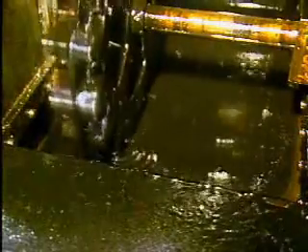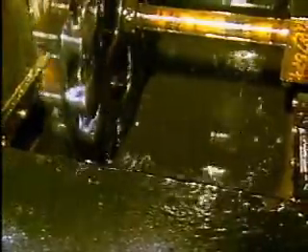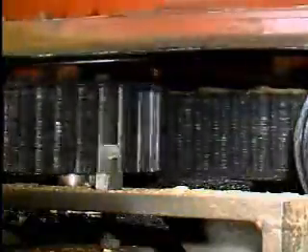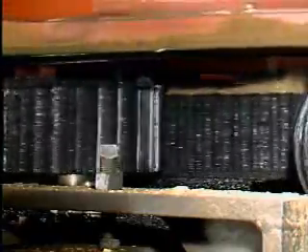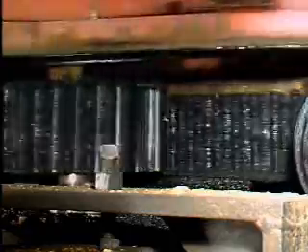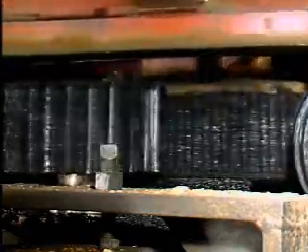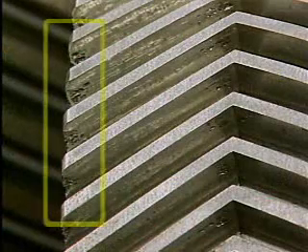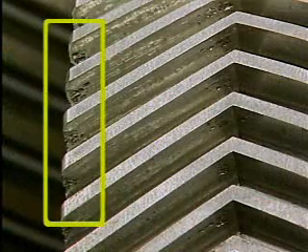Temperature may also become a problem if it's too low. If the temperature is too low, lubricant flow may become restricted, which robs the gearbox of its lubrication. Another lubricant condition that can cause gear problems occurs when lubricants become contaminated with dirt, sand, metal particles, sludge, or acids. Contaminated lubricants may cause a rapid erosion of gear teeth, which can cause teeth to break.